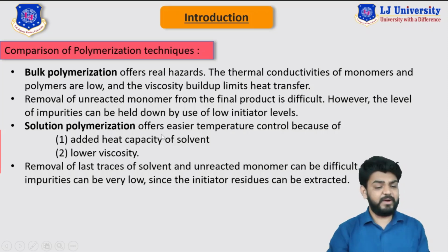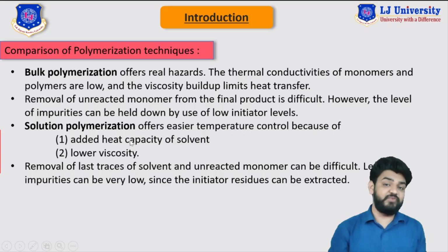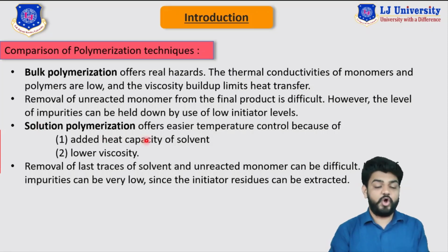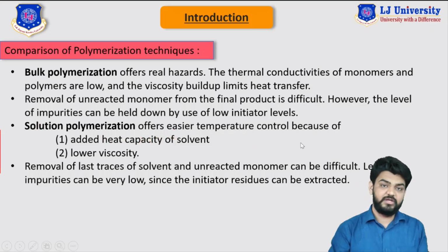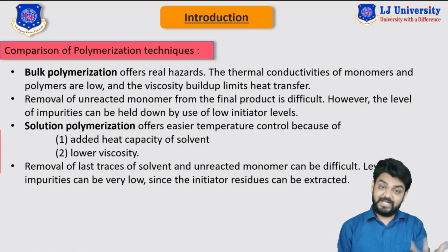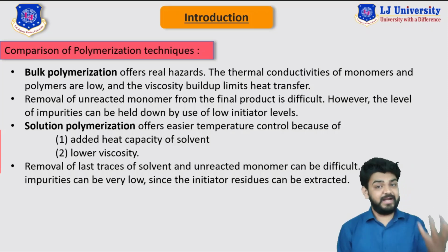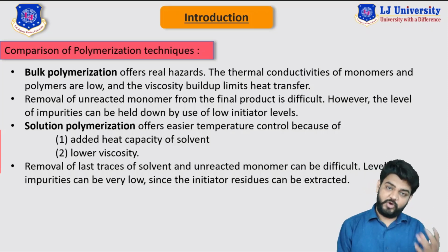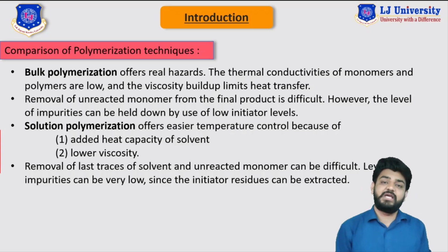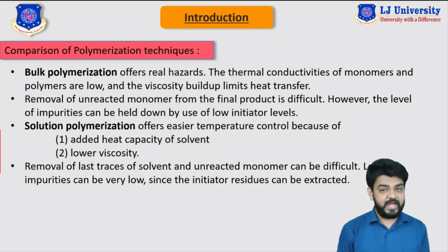Now if we discuss the solution polymerization technique, and if we compare the solution polymerization technique with others, we can say that this solution polymerization technique offers easier temperature control. So we have seen that this solution polymerization technique offers better thermal conductivity and better thermal control compared to the bulk polymerization, because in the bulk polymerization the product produced is in the solid form and which accumulates at the bottom of the reactor and which ultimately increases the viscosity, right?